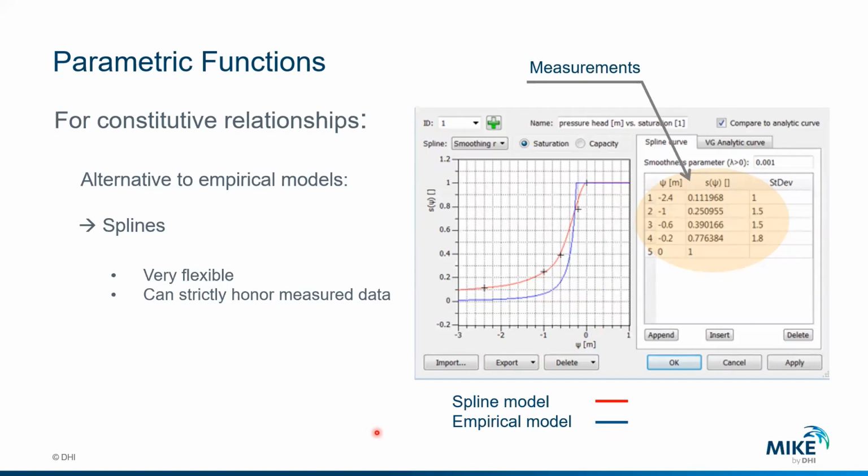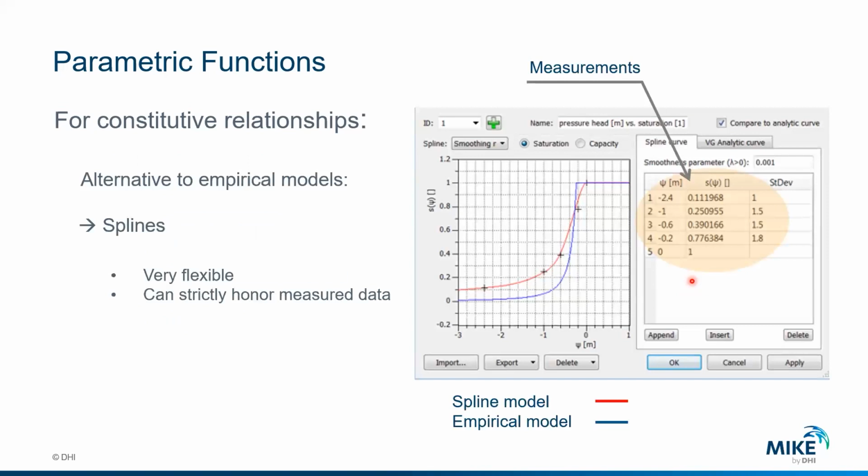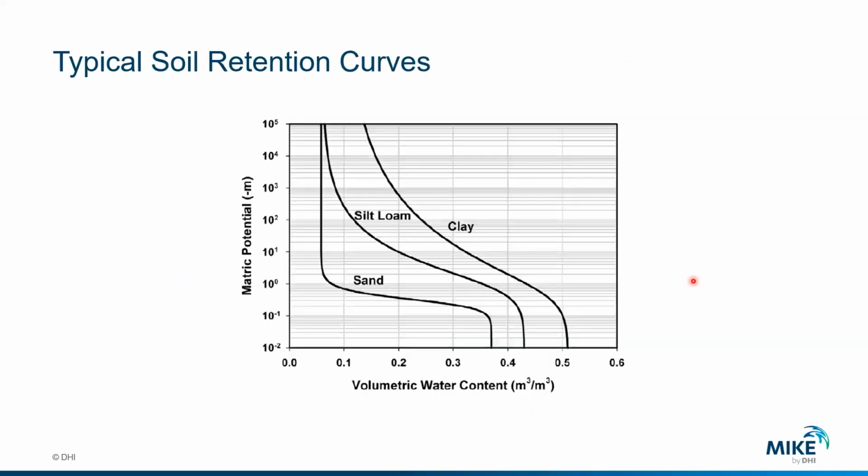I used to do this many years ago, and for that you need soil cores, which collect a small volume. Then you apply a certain vacuum to the sample, and start draining and measuring the pressure and the saturation, so you can come out with the soil retention. Normally, in regional hydrogeological studies, they do not collect such data. So basically, most of the parametrization is based on either literature values, manual adjustment done by calibration, or expert knowledge. So we talk about these different retention curves.